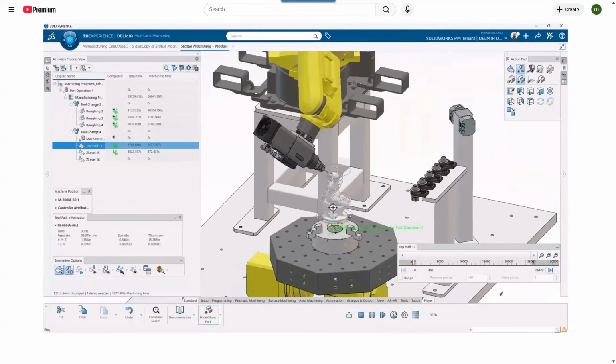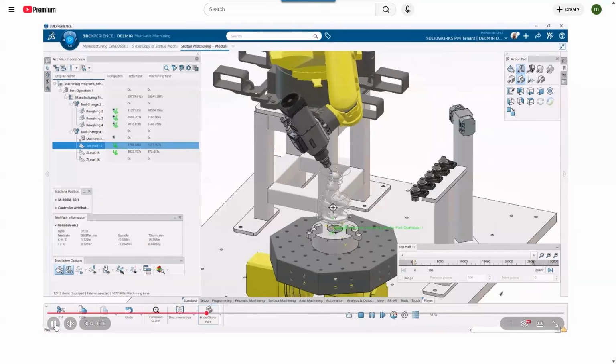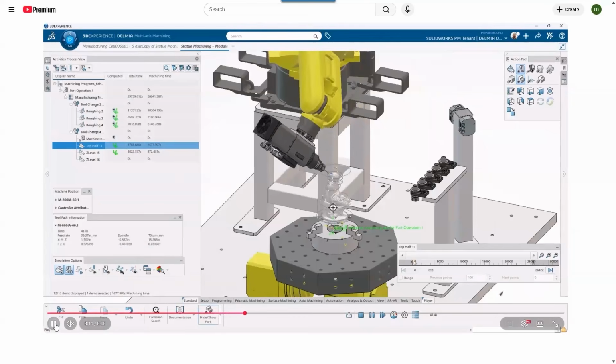We can also do laser, water jet, and plasma with the robot as well. We can do machine tending from this, so we have full interop between them. The advantage of our advanced manufacturing toolpaths, or advanced manufacturing suite, is I can jump between robot programming and arc welding and pick and place into machining and do machine tending or machining with a robot. This is an example of a scanned in statue. It was scanned in, converted to surfaces, and then from here, we're actually doing the machining and the toolpath on it, and we're letting the software figure out the kinematics in the joint.